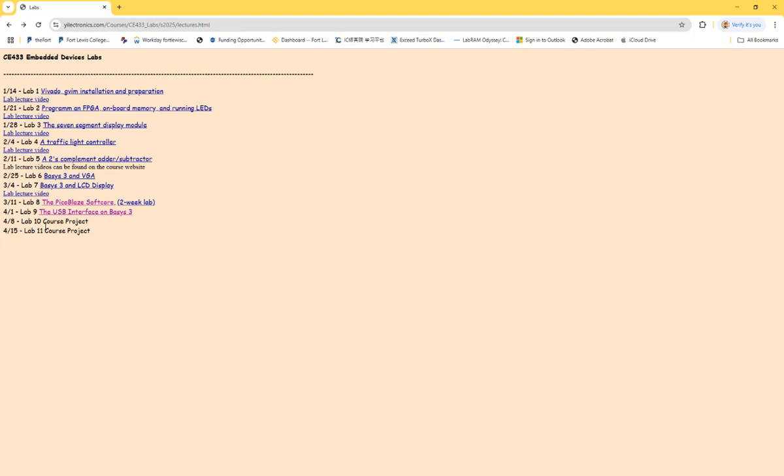So eventually, everything has to be controlled in assembly, and we don't have libraries available like Arduinos. There are libraries everywhere: you just load the header file of the LCD, throw numbers to the LCD through the APIs and functions, and eventually can display something. Here, it takes one entire lab session to display something on the LCD.